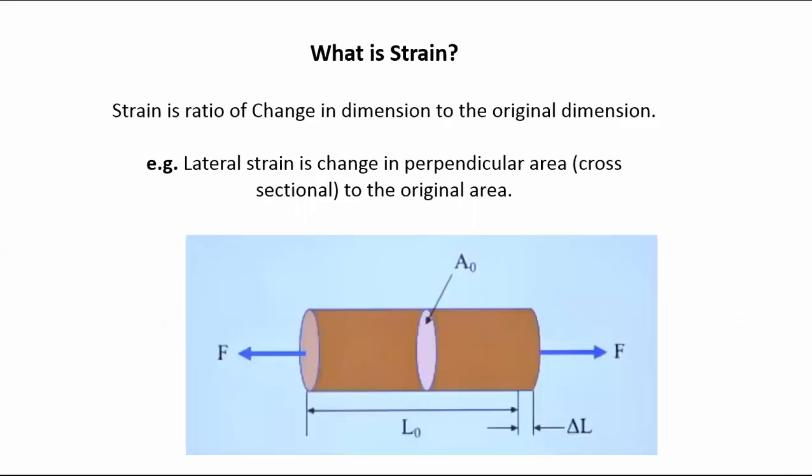The engineering stress strain diagram assumes that the cross-sectional area is constant even after applying force, and there is an elongation. This is for our ease of calculation, because we engineers like things a little easy, and it has practical application and significance. You can also draw a true stress strain curve.